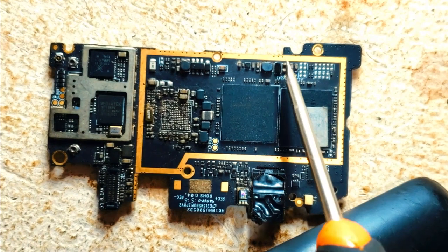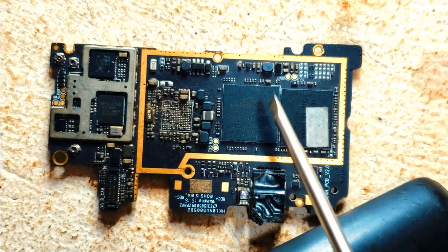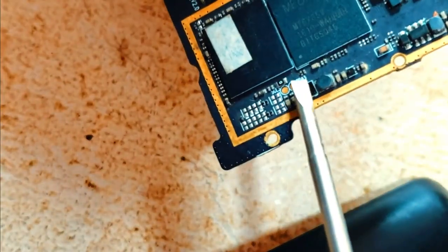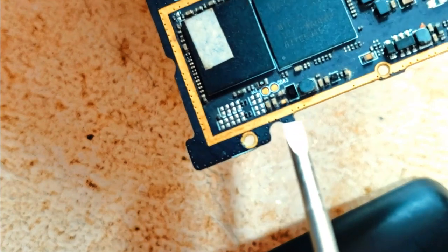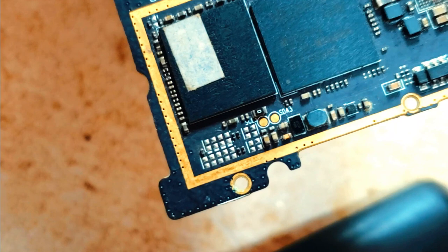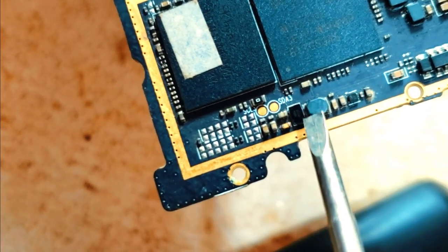How to identify display or graphic IC in mobile. The display IC is found in the power section of a mobile phone, specifically near the backlight section, which we will talk about later in this video, or around the display connector. You can identify it because of its glassy surface. Well, the display IC is integrated with the CPU in most phones. Only 30% of phones have their display IC separated from their CPU.